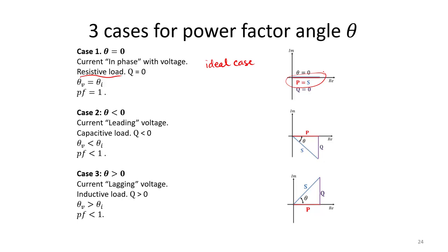But most of the time, we are unable to achieve this ideal case. Typically, we end up being in this lagging case. In the lagging case, we see that our reactive power Q is positive and our load will have inductive behavior.